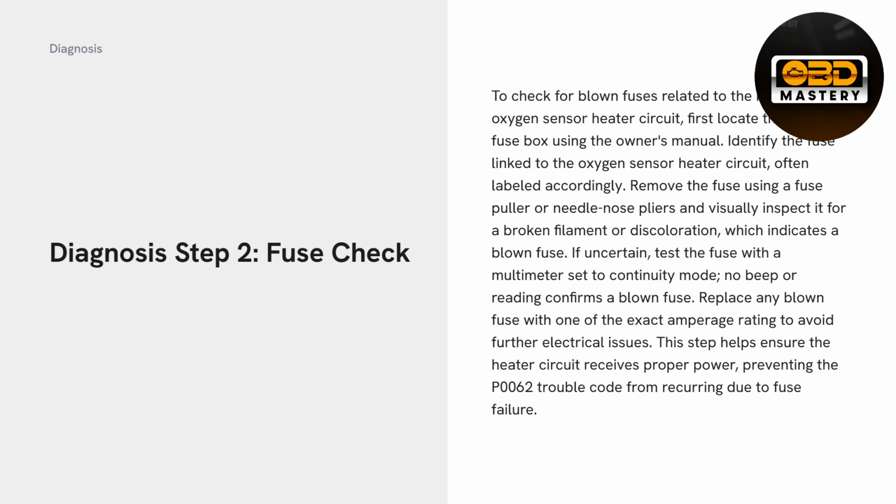Number 2 is just going to be a fuse check. So to check for blown fuses related to the heated oxygen sensor heater circuit, first locate the vehicle's fuse box using the owner's manual. Now identify the fuse linked to the oxygen sensor heater circuit, often labeled accordingly. Now remove the fuse using a fuse puller or needle nose pliers.